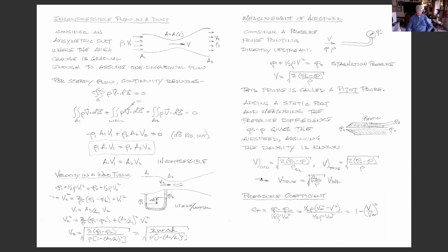speed of the airplane. And that gauge is calibrated for rho, but we don't know density, do we? Well, a pitot-static probe goes to a gauge, and in the gearing of the gauge to indicate the velocity that you want to know, it's assumed rho is sea level standard. Now, the true airspeed, not the indicated, the true airspeed looks just like it, except it's the real rho.